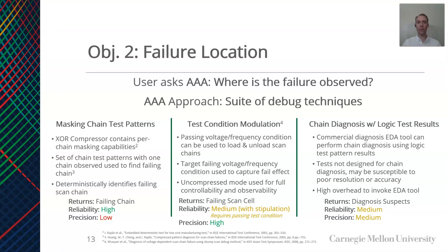for the shift procedure. Lastly, AAA can link to commercial diagnosis tools to execute a diagnosis run using the results from logic tests. The precision and accuracy of those results may vary depending on the distinguishing capabilities of the logic tests, but it will often be able to narrow down the set of potential failing scan cells from the full chain. However, there is runtime and compute overhead with the execution of EDA tools, so this is deployed only if